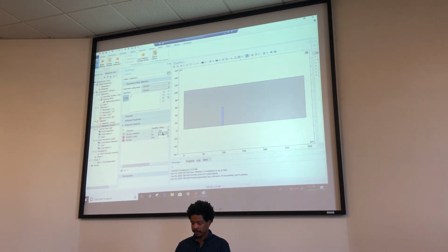Poisson's ratio for a lot of materials is a third, and for the density, 7850. So the density is almost 8 times the density of water. And the reason we need the density is because this is going to be a dynamic transient analysis, so it needs to know something about its inertia, its mass. So that's why density is being used here.